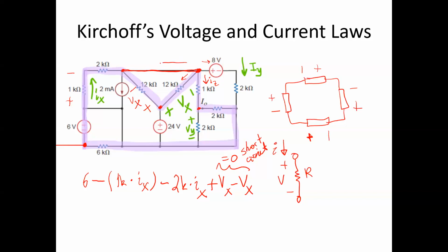You also have to add this current that comes through the short circuit connection. And that in turn is supplied by these other three branches. So another way of thinking about this is the same logic that we used to have with supernodes. If I draw a block around the entire supernode type of connection, then I have to add the currents on all of the branches that intersect with the box.